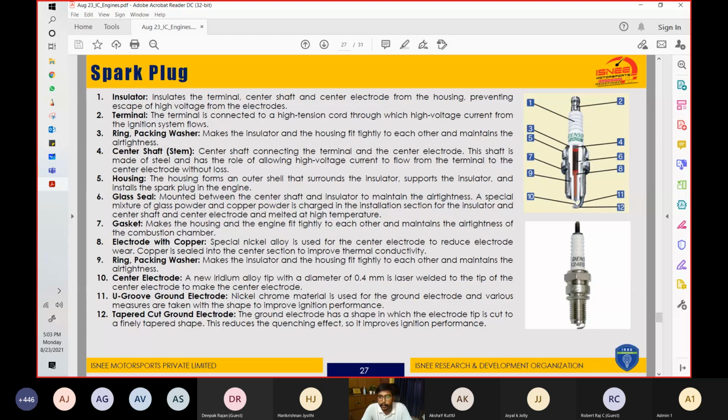What I'm trying to say is that when a mechanic repairs your engine and checks for the spark, the spark won't be visible if the spark plug is installed inside the engine. So they remove the spark plug from the engine, and then they connect the cable of the ignition coil to it, hold it with the hand, and then they just ignite the engine.